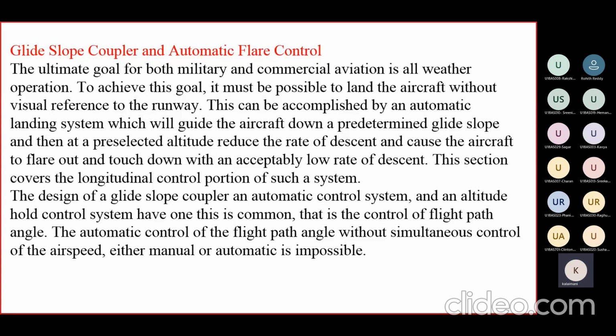There is a glide slope receiver that will be located in your aircraft. It will guide your aircraft to the pre-selected altitude. Then your localizer will help to align your aircraft with the center line. The marker beacon indicates how far away you are from the airport. Once the aircraft comes near the airport, each marker beacon is triggered.